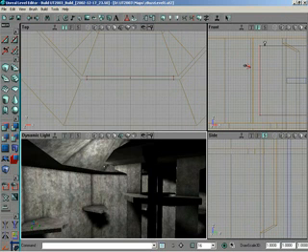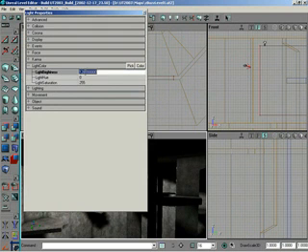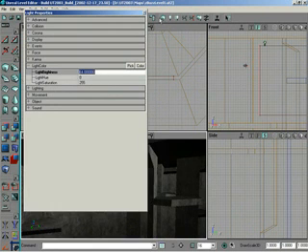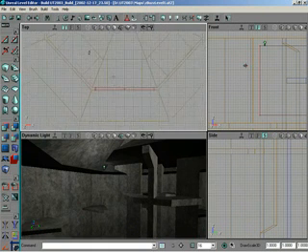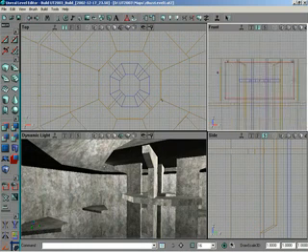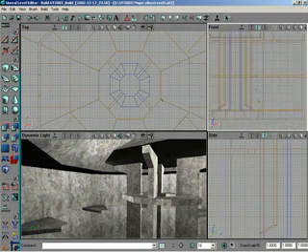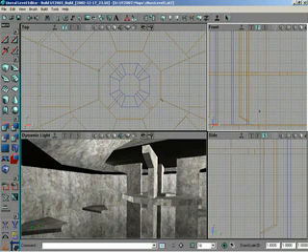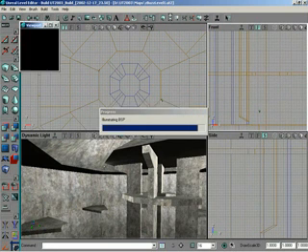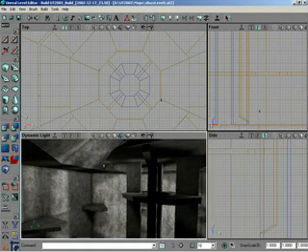Okay, I'll take this first light and drop its brightness by half, and then I'll duplicate it 2 more times. So dim it down a little. Let me find it in the top view. Control W, drag it to the other corner of the top. Control W again, then from a front view, let me drag that down almost to the ground, maybe just above that bottom pillar there. So that way we'll have illumination from the bottom as well. And I'll go ahead and rebuild lighting. Okay. All right, so yeah, that's a lot better, a lot easier to see what's going on.